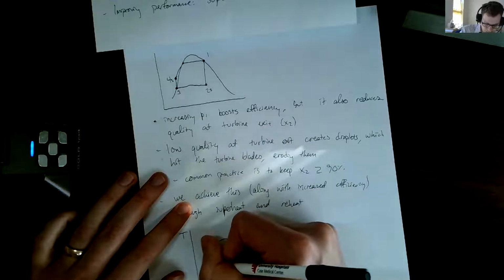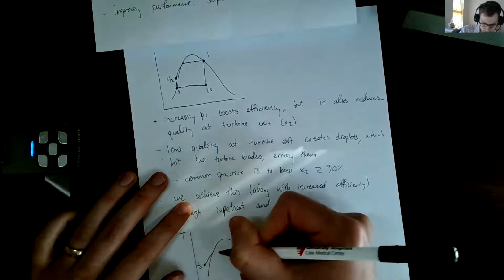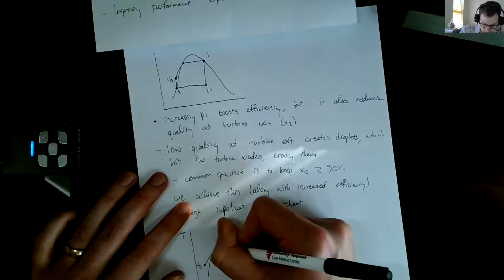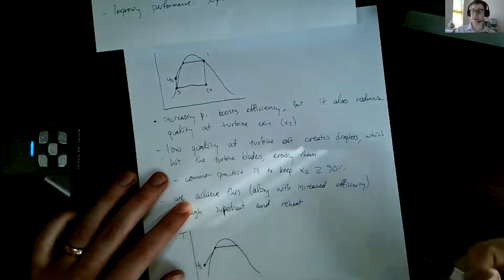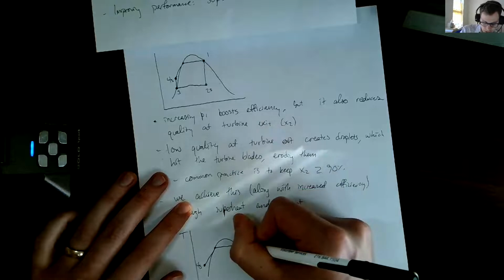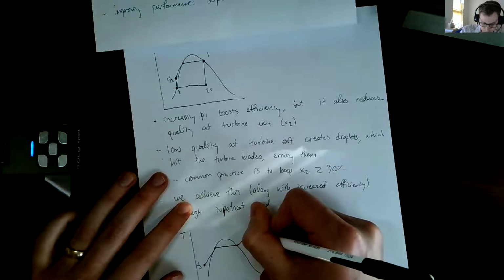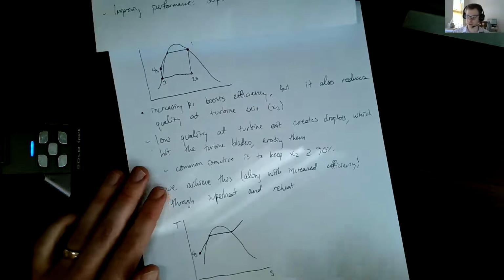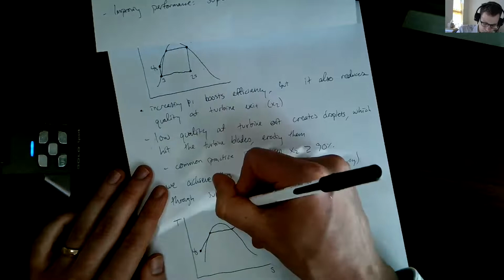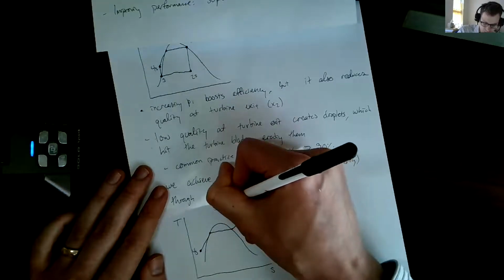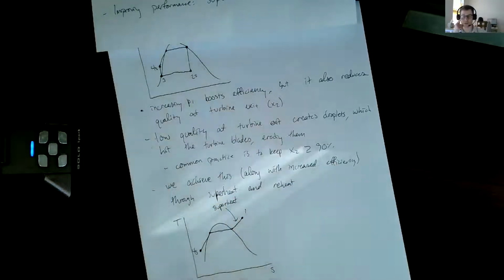So if we start at state 4S here, we heat along here at constant pressure, right? We hit saturation, we come straight across. And then instead of stopping, we just keep adding heat. It's still at constant pressure, but now the temperature is going to go up because we follow that isobar. So we actually heat all the way out to say state 1. Okay. And this part of it is what's called the superheat. We call it superheating because you create a superheated vapor. Get it? Superheated vapor, superheat. See how that works together?